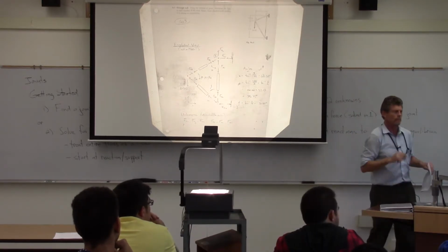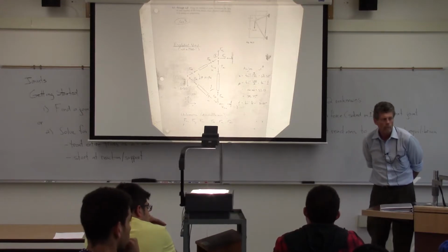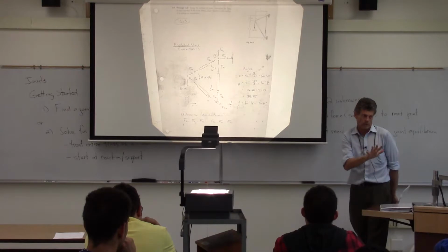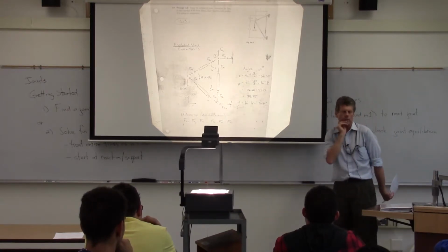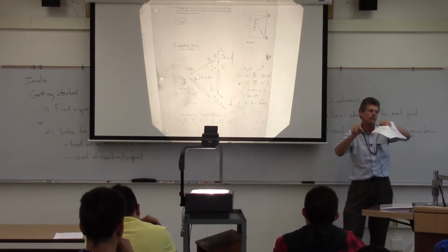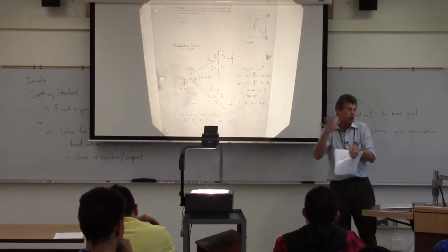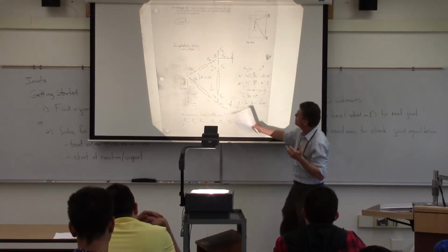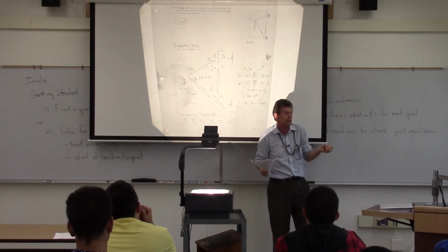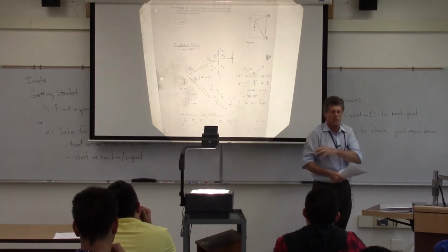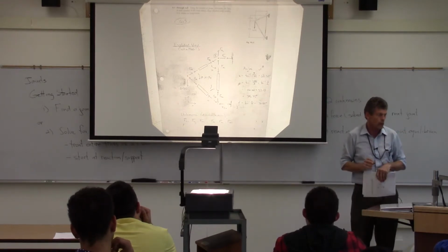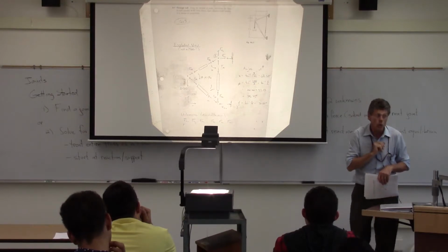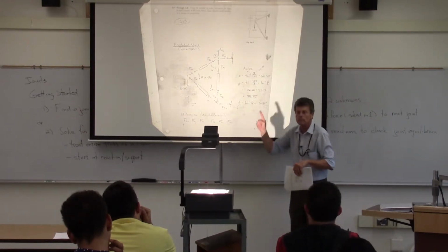Any other questions? Sir? Can you have it where part of the member is in compression and part of the member is in tension, or is it always going to be like this? In this analysis, now, if you get into finite elements and stuff, there's going to be bending where portions of the member might be in tension and portions might be in compression. But in this particular analysis, since we've assumed the members are two force elements, we're just going to assume it's the same force throughout. I'll save the other cool stuff for mechanics of materials. Any other questions?